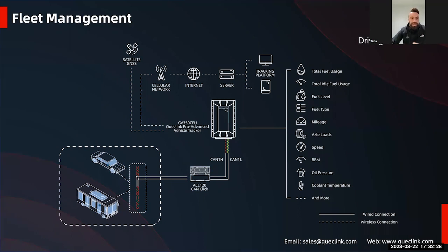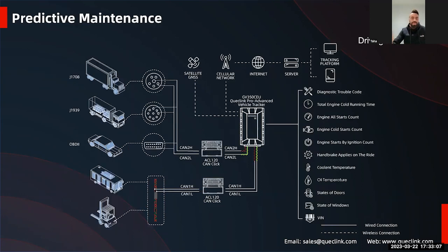Yes, after your installation is done correctly, the configuration is very easy. You just need to send one command and you can have a list of more than 30 parameters. You are very flexible to check them, check in, check out the boxes, and for all parameters you need, point the device to your server, and you can combine the CANbus data with the GPS. You can get all the GPS data, combine it with the health of the device, for example, external battery, status of inputs, outputs, along with the CANbus. Yeah, and here we go. Now you are very good to get your CANbus device.